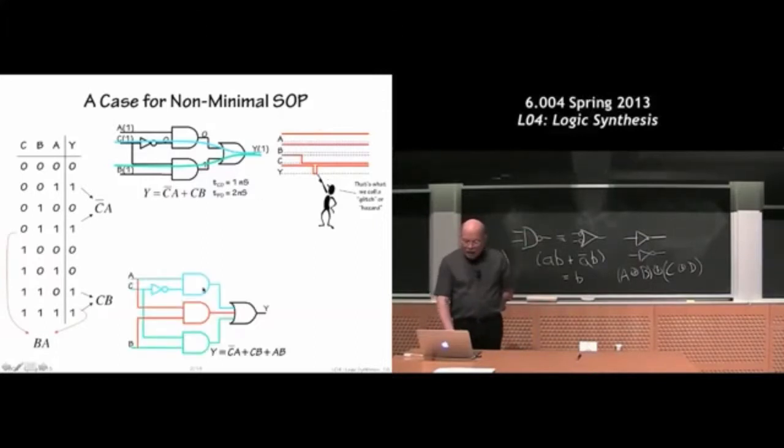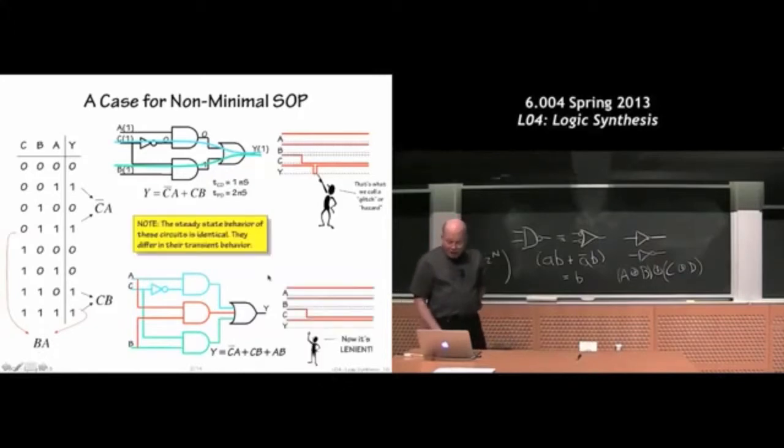What I'm going to do is add a third AND gate. I'm going to pick 2 more rows in the truth table here and build another product term out of them. This particular implementation involving these 3 product terms is functionally equivalent. The truth table of both of these circuits is the same. Y is the same. The advantage is that this circuit has no glitches when C changes.